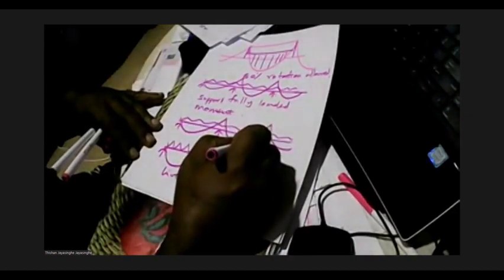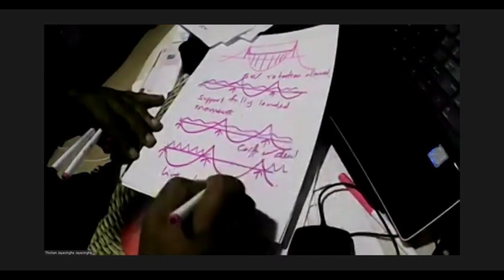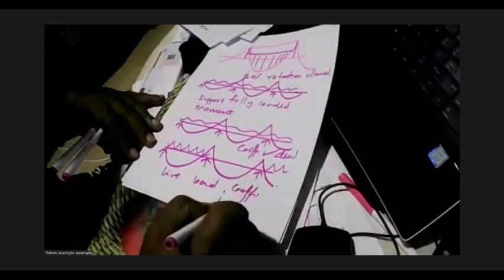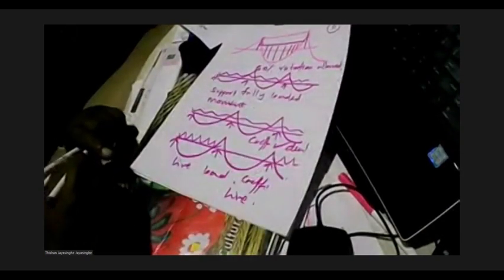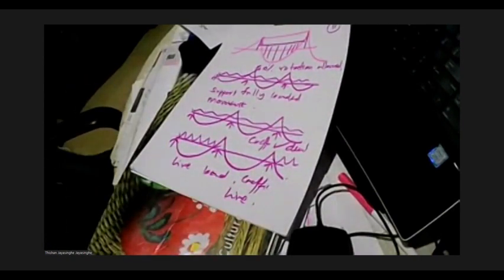So we want one set of coefficients for dead, another set of coefficients for live. So this is what I would like you to appreciate. We can't get the bending moments directly from one set of coefficients for dead and live loads. For live loads, we have to consider the pattern loading.